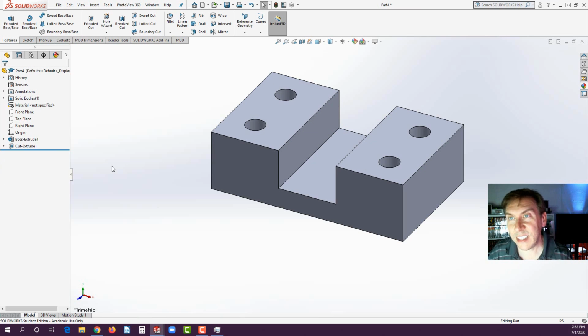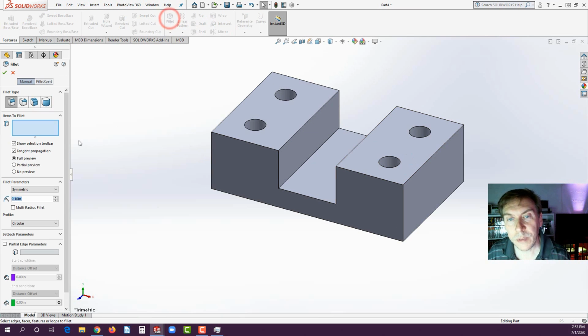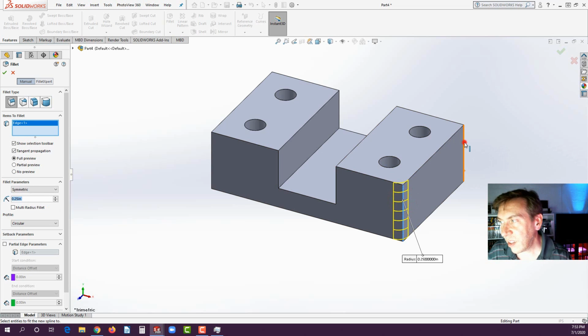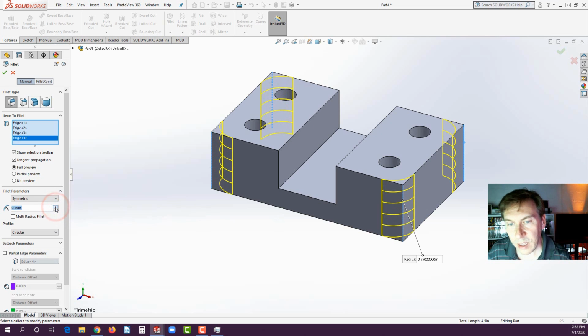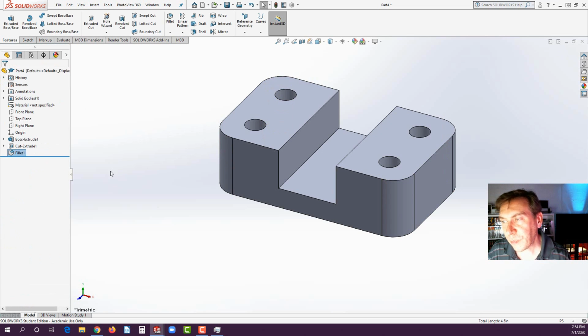Again, try enhancing it. Go to the fillet tool if you like. I love fillets and these features because really easily you can make something look genuinely complex and interesting. So I'm going to put in 0.25 fillets. We'll fillet this edge, this one here, use Superman Vision there, click here. I'll increase that a little bit. Let's put some nice big ones on there. 0.55 looks pretty good. Hit the green check.